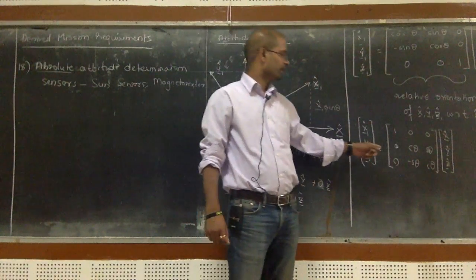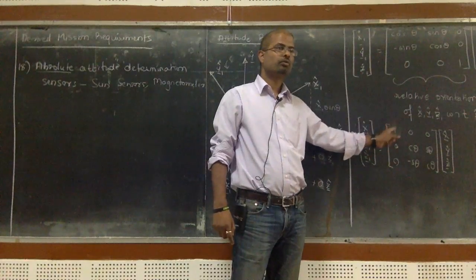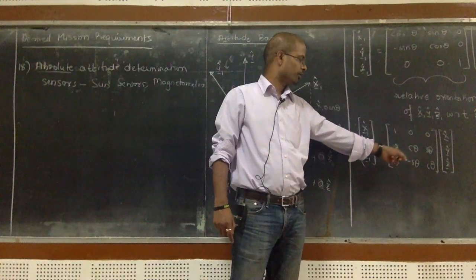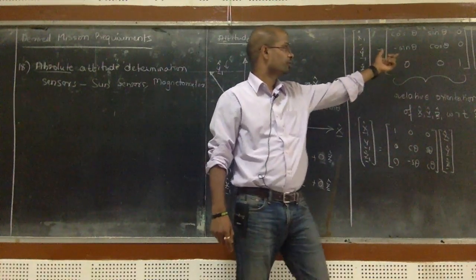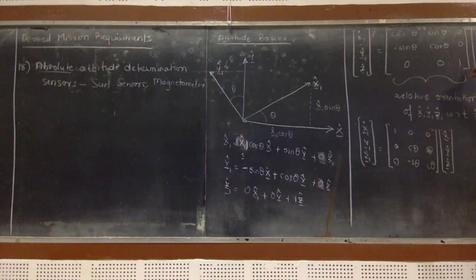if you rotate it about the x axis, this is what you would have got. So it is 1, 0, 0, 0, cosine theta, sine theta, 0, minus sine theta, cosine theta. So this changes. If you see, the z matrix is about the third axis, right? The element in the third row and third column is 1. The remainder are 0. And then you have cosine, sine, minus sine, cosine. And similarly, since this is about x, you have the first row, first column as 1, then 0, 0, cosine, sine, minus sine.